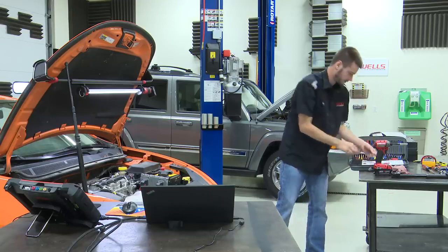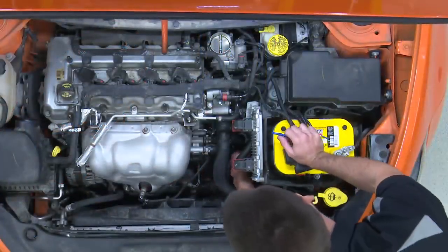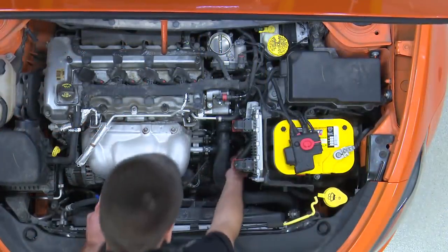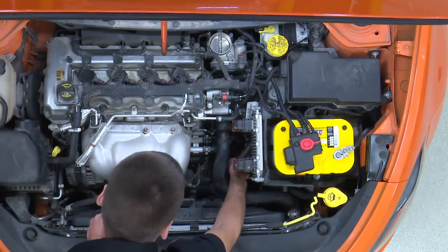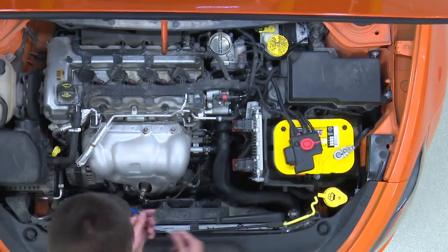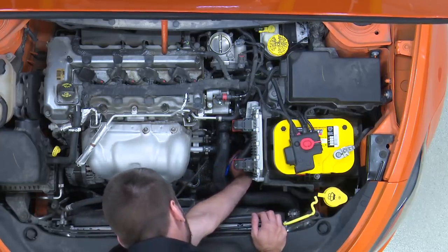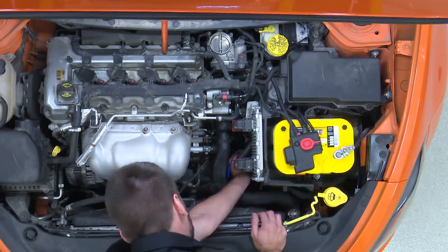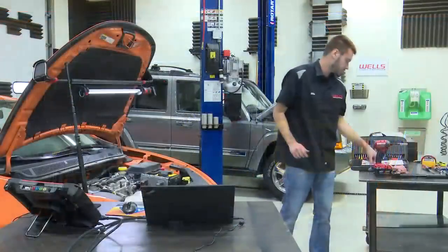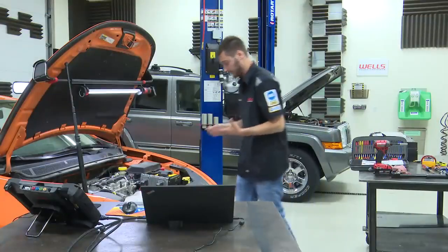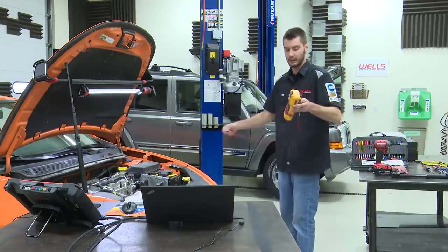All right, so I'm going to unplug this, and what we're doing is we're just going to go right on the transmission range sensor side. Connector's unplugged, and all I'm going to do is ohm across this sensor. So I'm going to go from pin 3, maybe. All right, maybe that's on there. I can't tell. So already running into issues with, I don't know, is it connected, is it not? I can't see in there. It's kind of a pain to get to.